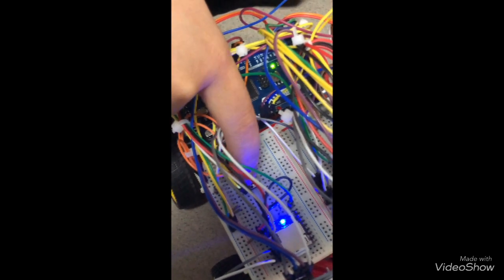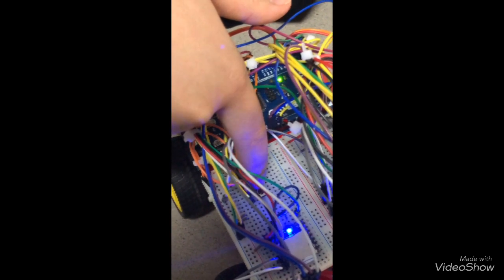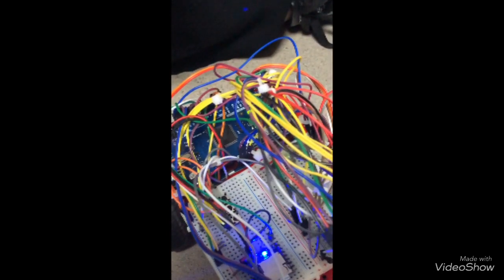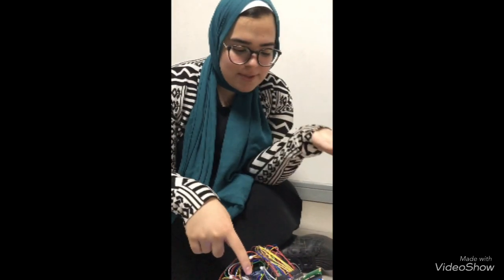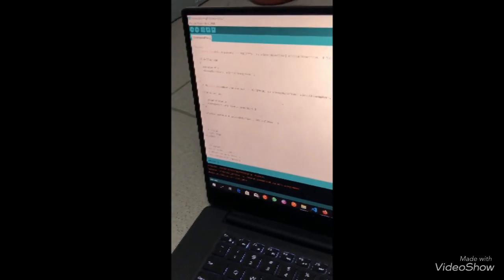Here is the song working. If we decide to press previous or next, everything's working. So the song is playing. If you try to press previous or next, we go to this code. If we press next, we try to take the semaphore and wait for only 5 milliseconds so that the code is not blocking. If we could take the semaphore, we play next, then give the semaphore back for anyone who wants to use it.